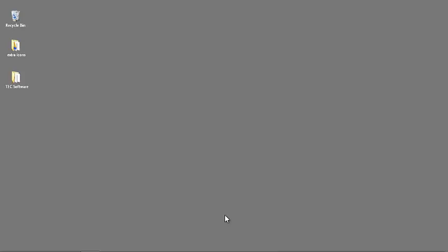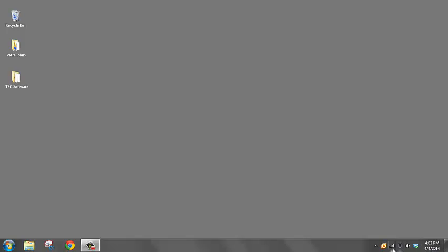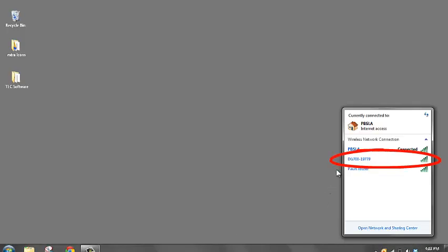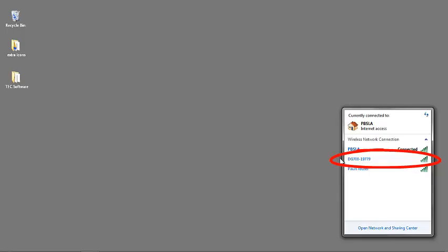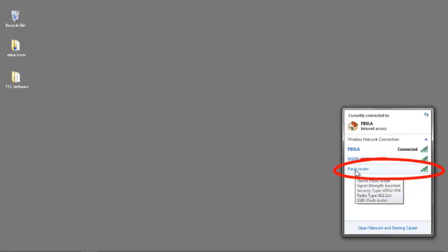For this TECLOG3 demonstration, we're using 4 DG700 gauges. 2 of them have wired connections and 2 have Wi-Fi connections. So the first step is we'll look at our Wi-Fi networks, and we can see that one DG700 is still in the AP direct connect mode and is showing up as a network connection. And then we can see our router also, because we can only connect to one network at a time. If we're using more than one Wi-Fi device, we need all of those to connect to a router, and then we connect to the router